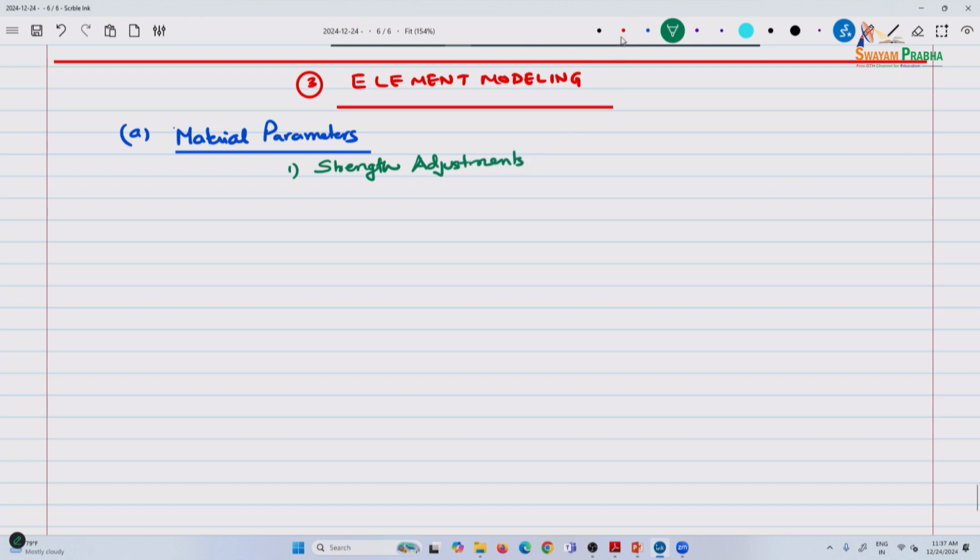And two of them that are commonly used are the strength increase factor. Especially concrete over time does gain some strength, and you account for that. It's typically older structures that are subjected to these types of loads, so you account for what are also known as SIFs.